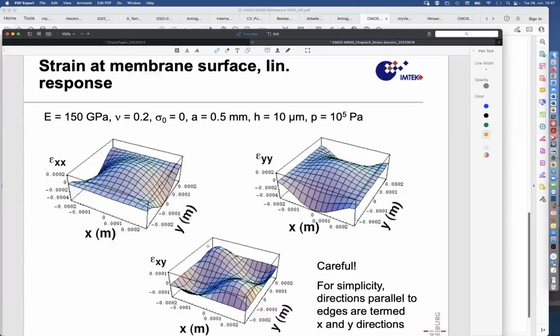So if you wanted to apply a shear stress sensor, you could place it somewhere here in these alternative locations. And you know how a shear stress sensor might work. I mean, a shear stress sensor is also a Wheatstone bridge under appropriate rotation, and then you could calculate the sensitivity, and you would for sure find that actually it's unfavorable. These shear stresses are smaller, and the piezoresistive coefficient you can apply with the sensor elements are not so favorable, and so you can drop the shear option.